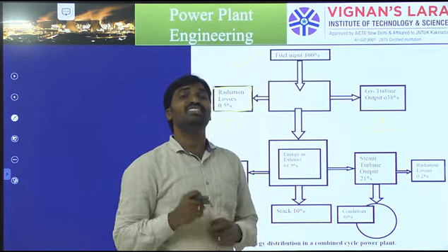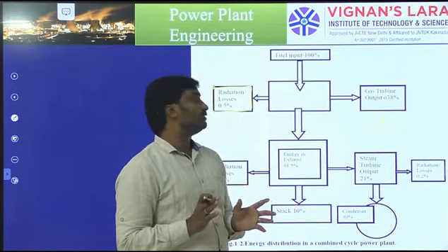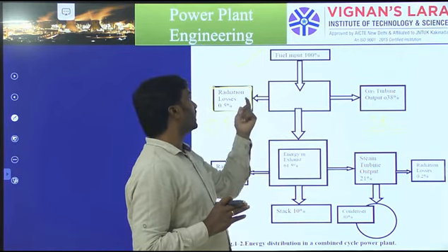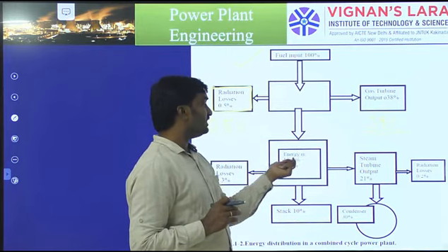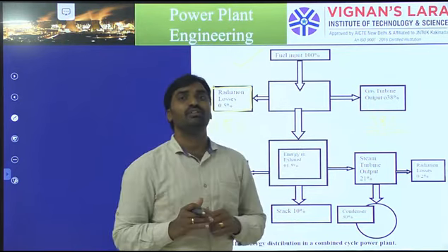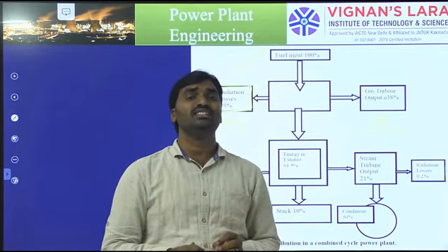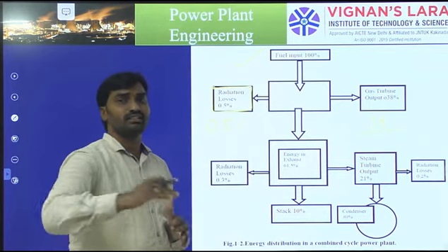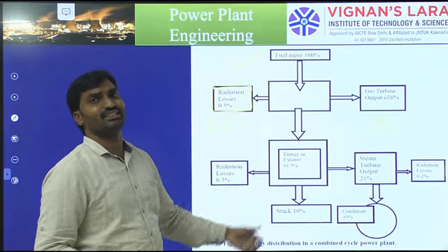What about the remaining 62%? So 62% of energy is wasted. Out of which 61.5%, because the radiation losses are 0.5%, is the energy in the exhaust gas. So I would like to utilize that 61.5% and generate electricity from the wastage of exhaust gases.